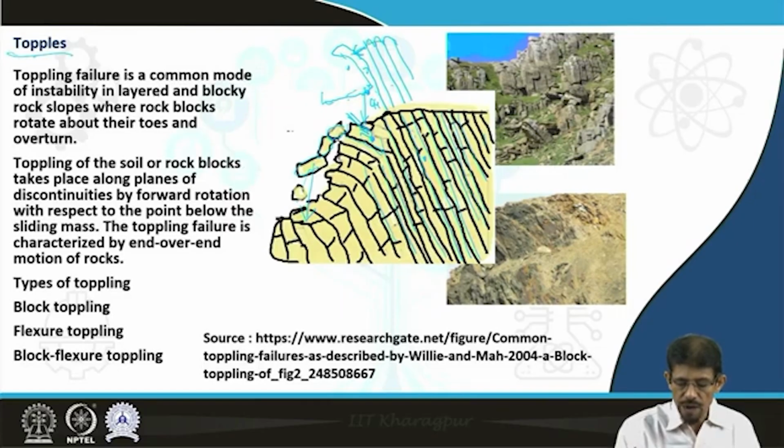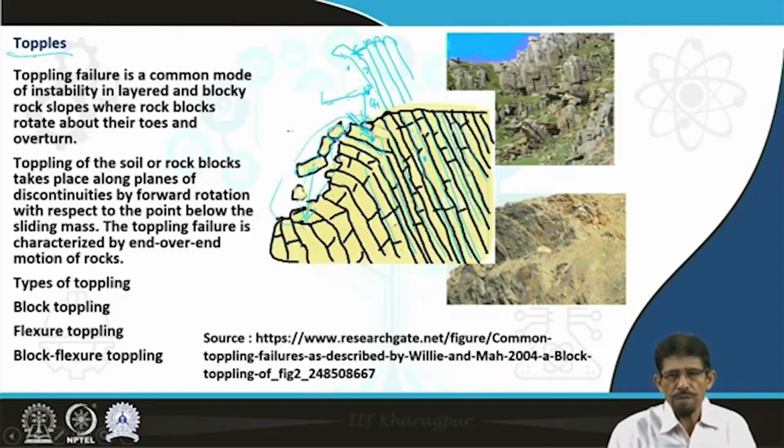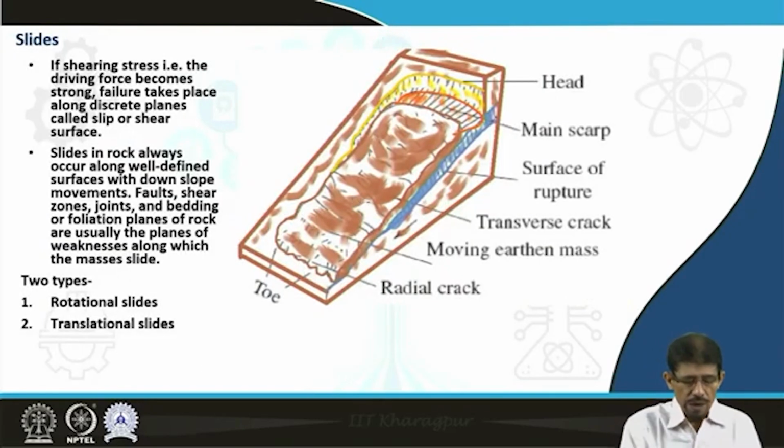started tilting, and finally they detach. This type of slides we generally experience in case of extended rock strata traversed by a number of discontinuities, or some layered strata traversed by one set of dominant discontinuity. This type of slides we generally encounter in case of columnar type of joints, prismatic type of joints, if present in rock strata. Next term is related to slide.